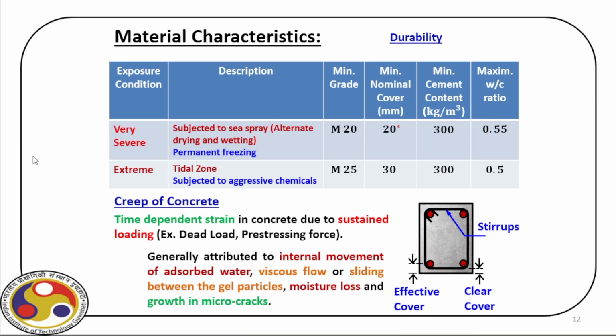Now, beyond shrinkage and durability, creep of concrete is also equally important. And what is it? It is time-dependent strain, right? When the concrete is under sustained loading, for example, we have dead load, prestressing force, under this loading, the concrete undergoes some kind of strain, and that is what we call creep strain, right? Now, in our design, we need to take care of this creep strain.